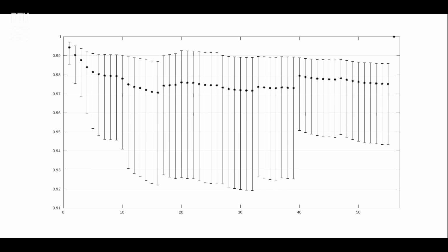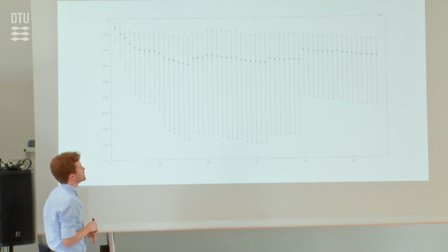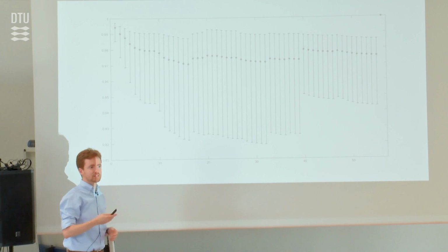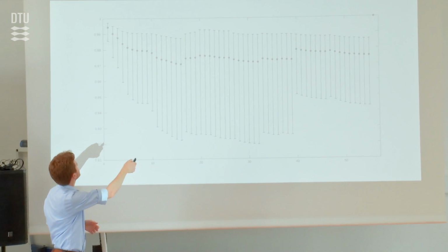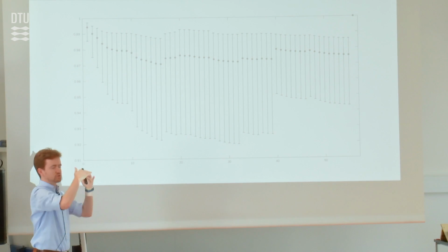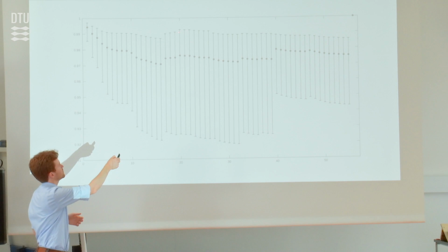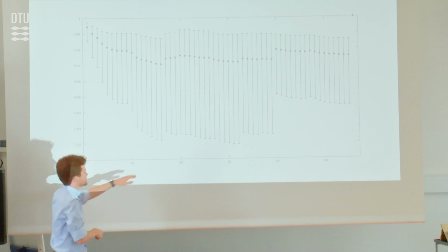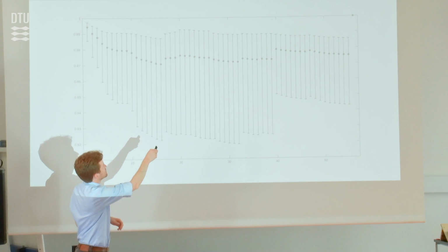This is the voltage. The way I created this script is that with all the data collected from real power demands, the bar indicates the median, the star indicates the median of the voltage, and this is the 95% of the cases. Meaning in 95% of the cases, my voltage was below 0.99 something. So it was very conservative here. I could have injected much more power because this is far below 1.02. If I do things properly, then these bars should be close to 1.02 because these bars are the 95 percentile, 5% percentile, and the median.